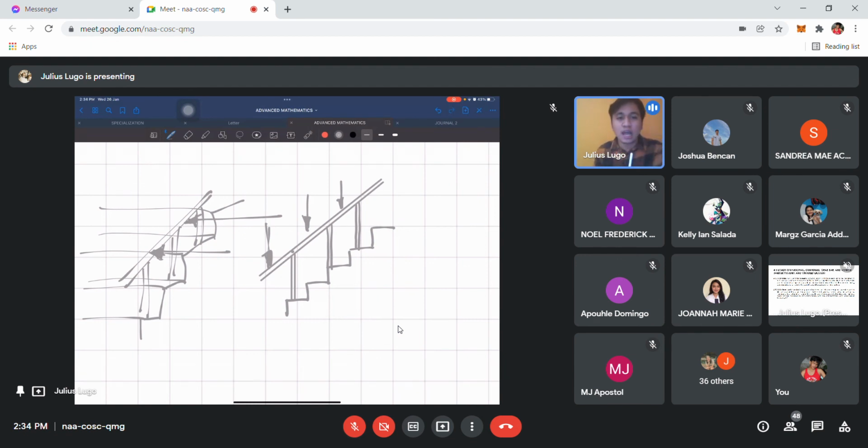Okay. Then how about uniform load? So handrails and guardrail systems shall also be designed to resist a load of 50 pounds per feet, or 0.73 kilonewton per meter applied in any direction along the handrail or top rail, and to transfer this load through the supports to the structures. This load need not be assumed to act concurrently with the concentrated load specified in section 4.1.5.